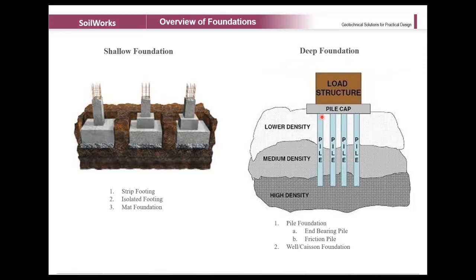So where your foundation will surpass all the low density layers and goes to the higher density or rock layer, so that the strength will be transferred from your load, your superstructure, directly to the high density rocks in the very lower layers. So that's your deep foundation. And apart from this, we can combine the raft and your pile to have a pile raft foundation.